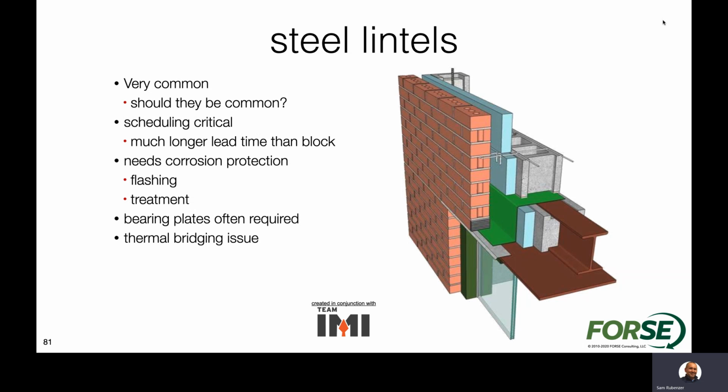So you really have a steel element that's going to be changing size, changing length, when the rest of the masonry wall that's behind insulation, that's a lot more mass, is definitely not going to have the same conditions. It's not going to be changing size. So that really does have some demands and create some bearing issues for those steel lintels.